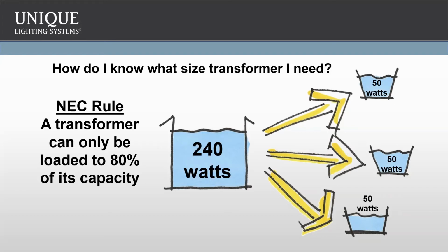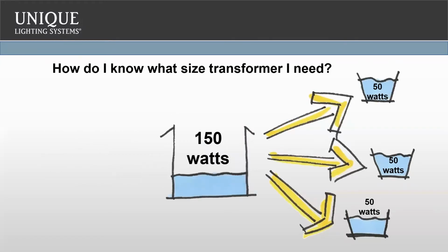If I go to the next slide here, if I use the 150 watts, I still have 90 watts of reserve. That is killing me. Without that rule, I'd have 150, but now I still have 90. So I still have room to be okay with sizing this transformer.